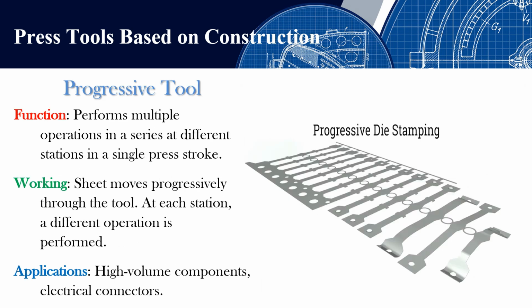Progressive tool. Function: performs multiple operations in a series at different stations in a single press stroke. Working: the sheet moves progressively through the tool. At each station, a different operation is performed. Applications: high volume components, electrical connectors.